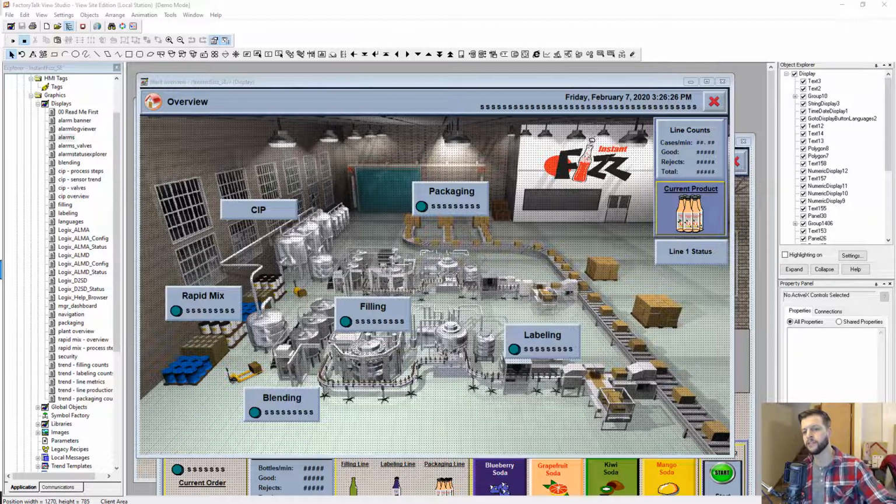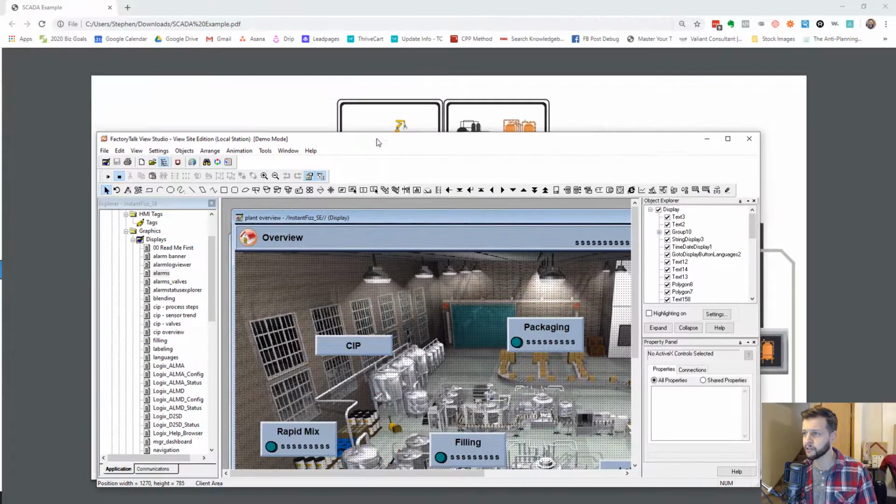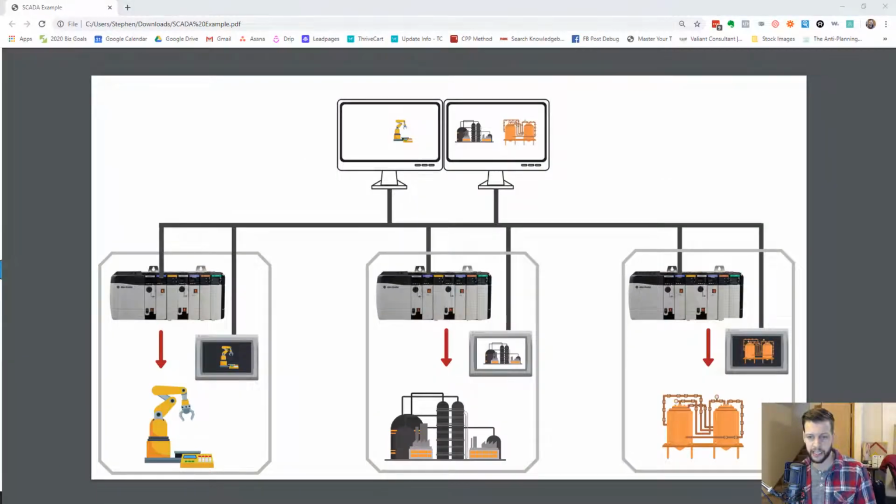And it combines that data from those various controllers into a centralized system, such as the HMIs we discussed early in this lesson. And it gives the operator the opportunity to respond to alarms, monitor the system, monitor system variables, and/or perform high-level control actions such as starting or stopping a machine or process or jogging a motor and so on.